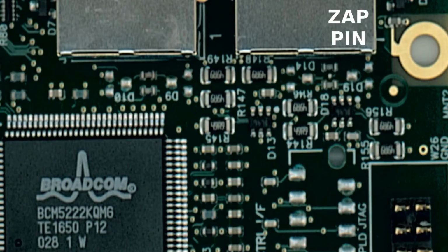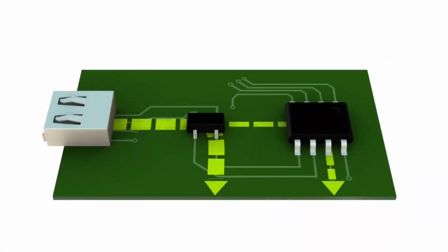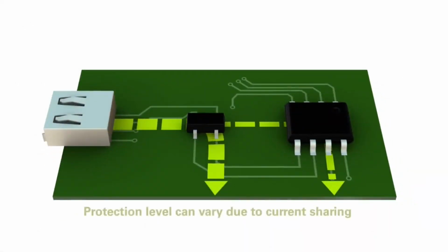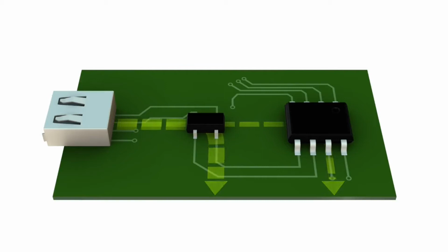Again, if we watch it, we see the current flow into the TVS and then also some residual current flows into the ASIC. The residual pulse is the critical element that we have to understand. How is the current shared between the TVS device and the ASIC? While we often hope that the TVS will shunt most of the energy, how do we know if the ASIC can survive the rest? Consider this simplified example.